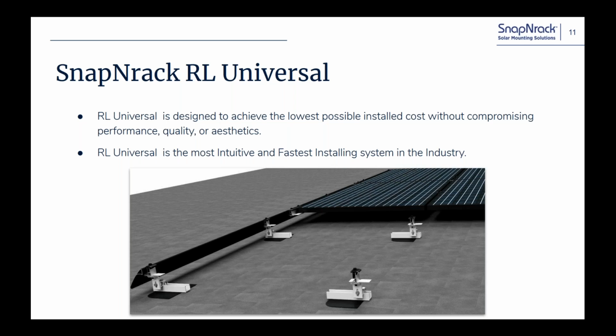So if you've got a rafter that is right where two modules come together, you can just make some slight adjustments to the location of the hardware, meaning you can flip the mount on the other side of the track, or you can slide the link over a little bit, whatever it takes, but you don't have to swap parts, change parts, or replace anything. What you see in this image here is the entire system. You've got mounts, tracks, links, and skirt. Very straightforward, very simple to install.